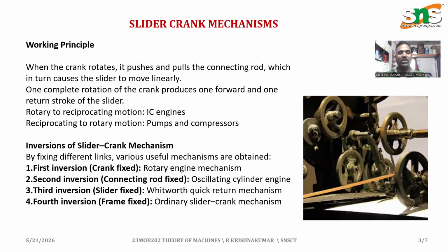Working principle. When the crank rotates, it pushes and pulls the connecting rod, which in turn causes the slider to move linearly. One complete rotation of the crank produces one forward and return stroke of the slider. Rotary to reciprocating motion: internal combustion engine. Reciprocating to rotary motion: pumps and compressors.